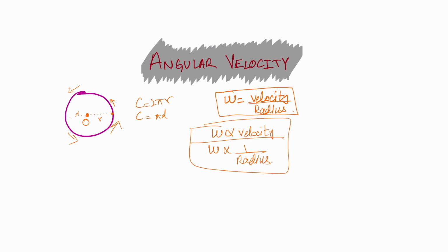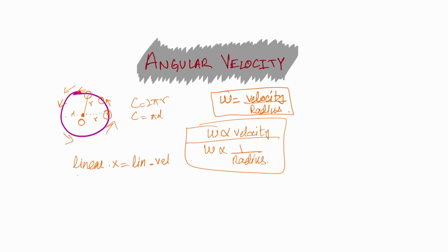The point is, whenever we have this relation applied, what it is actually doing is, if our robot is at this point, it keeps on moving along the boundary of a circle, that is the distance in radians, and this velocity is being directly applied through a linear signal, and this relation then makes the robot move in an angular motion. Specifically in our scenario, we are going to be giving the linear velocity to linear x, and angular z is going to be equal to the linear velocity divided by the radius.